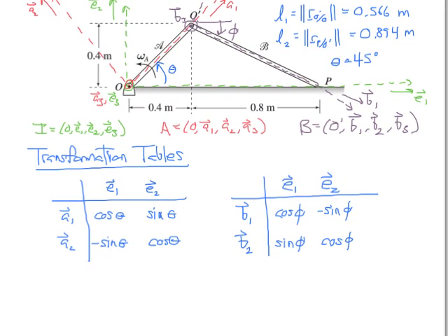And for the angular velocities, our angular velocity of reference frame A as observed in the inertial reference frame is theta dot in the A3 direction. In the book, we call this omega A in the A3 direction. And then the angular velocity of reference frame B as observed in the inertial reference frame is negative phi dot in the B3 direction. And in the book they call this just omega B in the B3 direction. So we'll use this notation as we work through the problem so we can stay consistent with what we see in the example in the book.